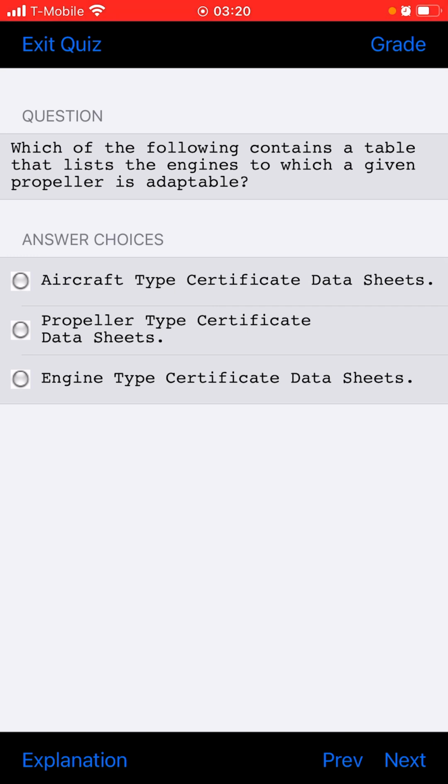Number 12. The following data concerns an installation. Electrical unit is known as current requirement for continuous operation, 11 amperes. Measured cable length, 45 feet. System voltage, 28 volts. Do not exceed 1 volt drop. Cable in conduit and bundles. What is the minimum size copper electrical cable that may be selected? Number 12.